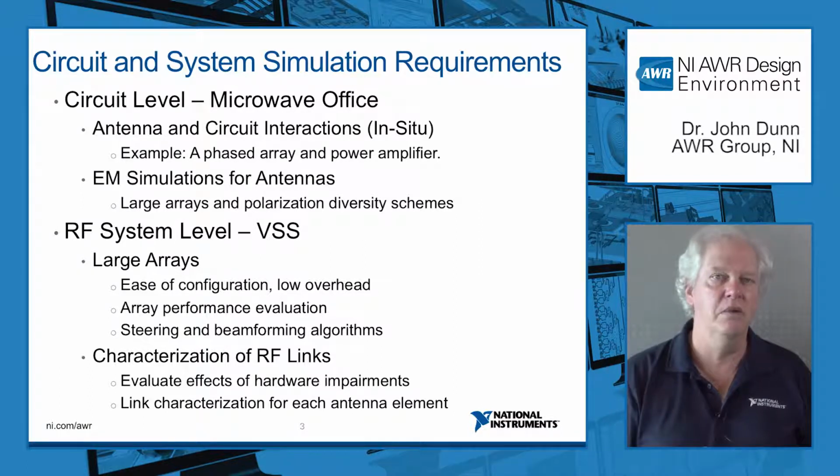As you steer the beam, the loads change. As the loads change, you're going to change the performance of the power amps. So they're really coupled together, and it is not sufficient to just run the EM and look at the antenna pattern, because it's not going to involve the power amp. So that's in situ type problems. I'm going to show you what our solution is in version 12 of Microwave Office.